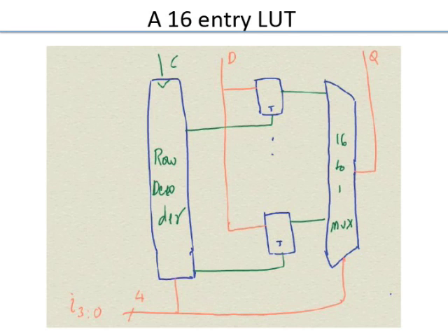I'll let you figure that out as part of your project. It's not that hard, but you should figure it out. You have a choice, and that's why I'm covering this: you can have either random access or serial access. Random access means more hardware but simpler control. Serial access is less hardware but more complicated control.